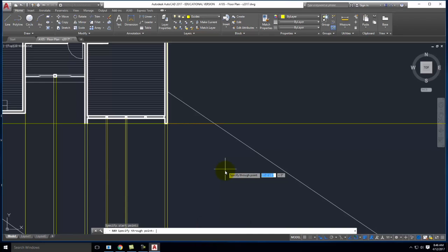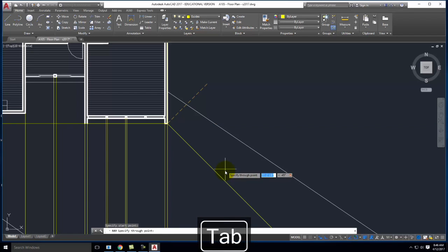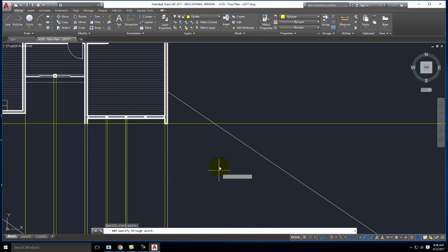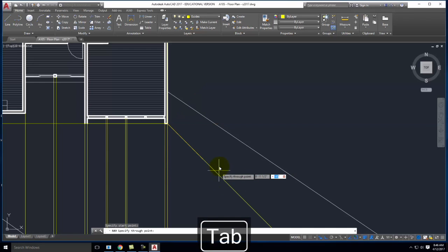There's a number, but then next to it there's a number for an angle. And so when I hit tab again, I now get into the angle. And so I can type -45, and then I can press tab. And it will now lock me into drawing only at a 45-degree angle. I have to do it again. So, all right, -45. And if I were to click,